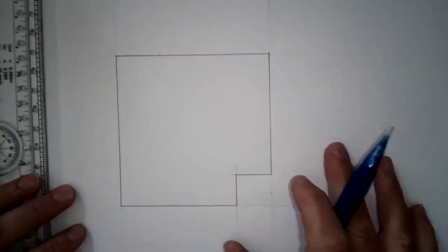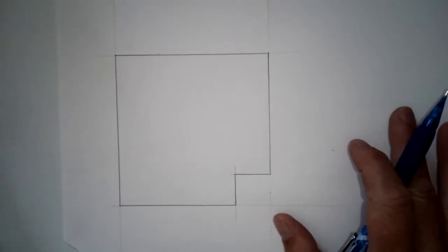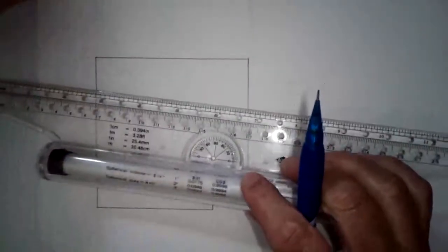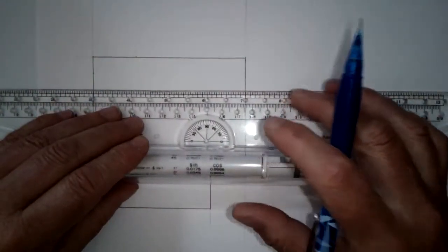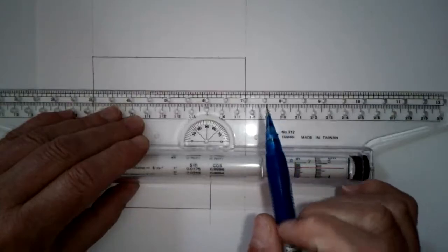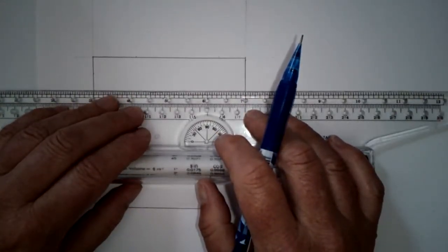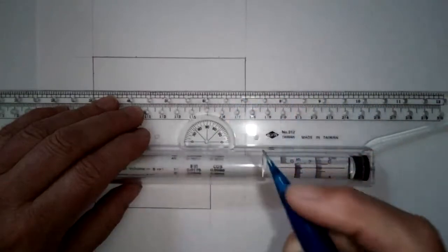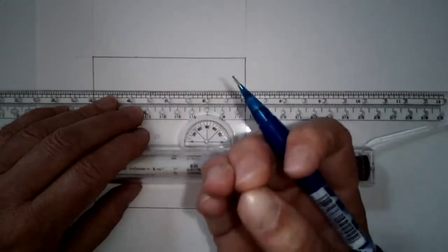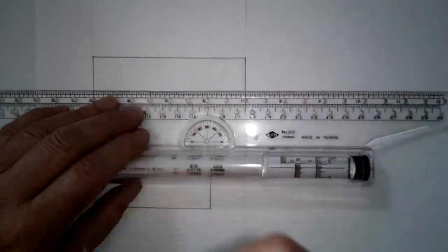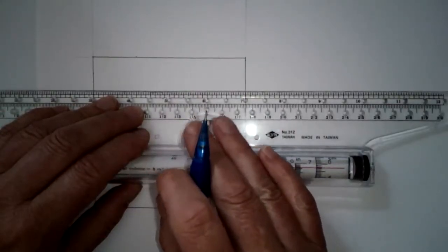So now we've got all of our object lines created. We're going to create some hidden lines. So hidden lines are thin, and what that means in mechanical drawing is that we still want it to be a dark line. Dark and thin or dark and thick are not the same things. Thick means the width of the line, but how dark it is is how much of the lead you're really pushing down and making sure it shows up nice and sharp and darkly on the page.